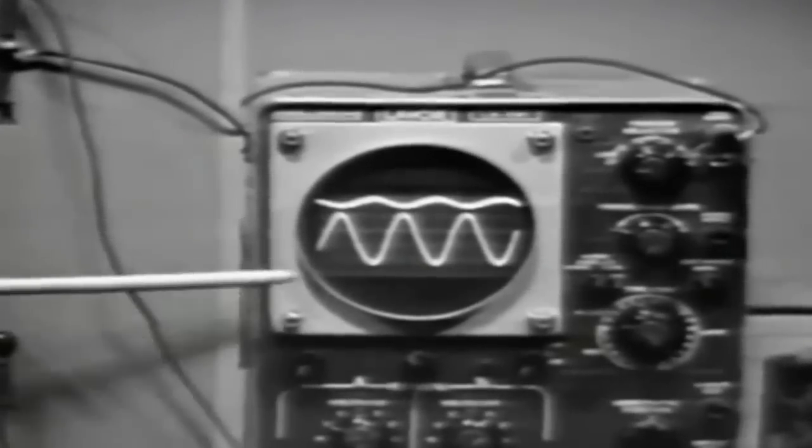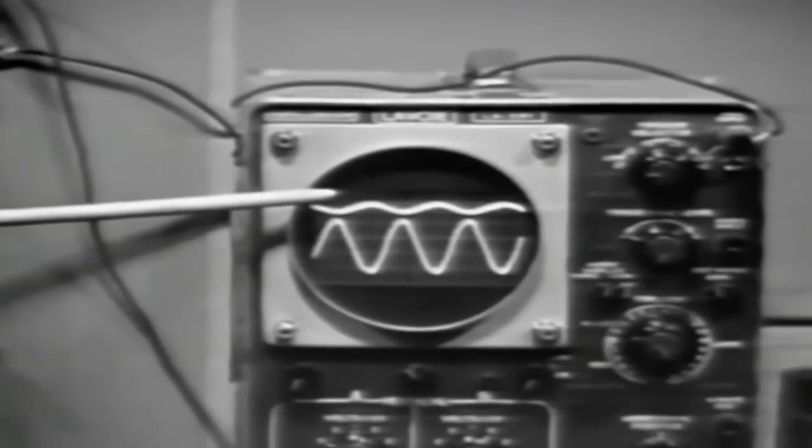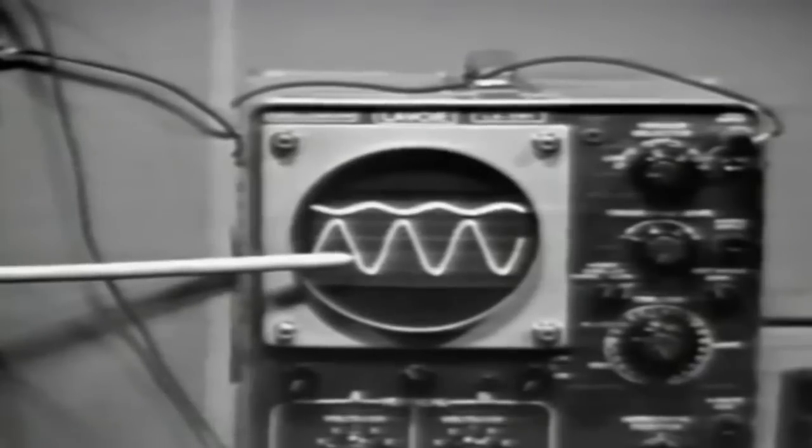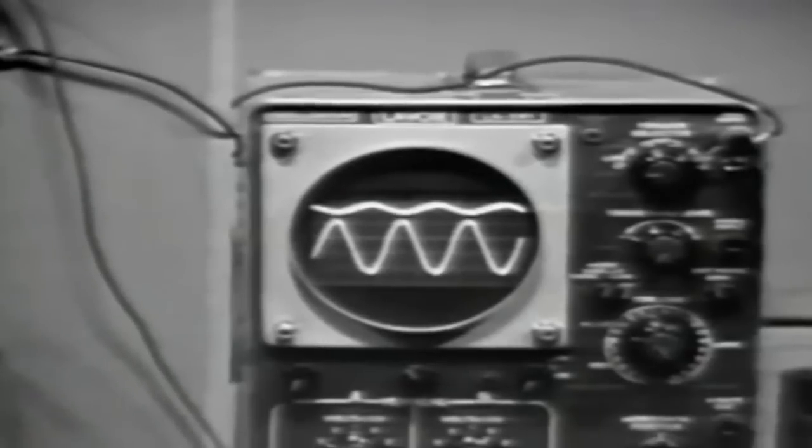The upper trace is connected to the input and is now reading 0.2 volts peak to peak. The lower trace is connected to the output and is now reading 5 volts peak to peak. So this way we can actually observe a wave shape that represents the amplified voltage. To summarize, we have gain in this amplifier because a small input current change causes a large output change.